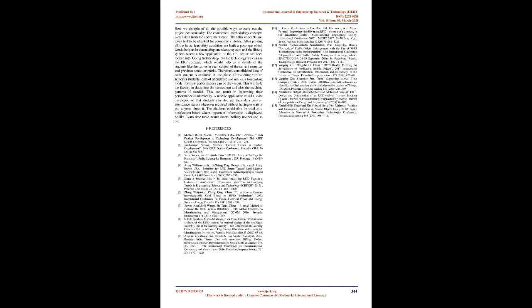So when a student passes through the first IR sensor, his tag gets activated and now he should pass through the next sensor, else the RFID reader would not sense the tag and the attendance won't be recorded. So after he passes both IR sensors his attendance will be recorded and his card number will be processed and stored in the micro SD card module used for the back-end system to verify the attendance status.